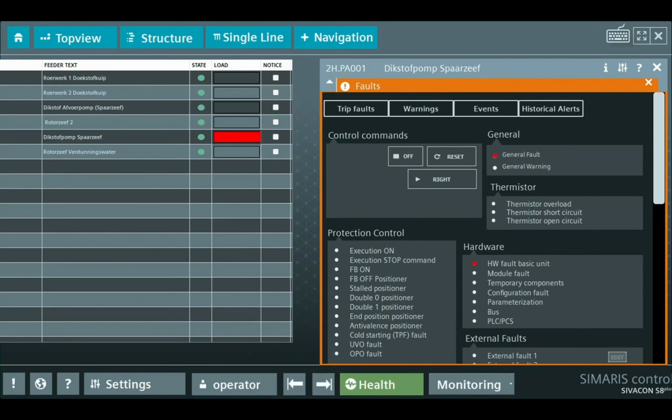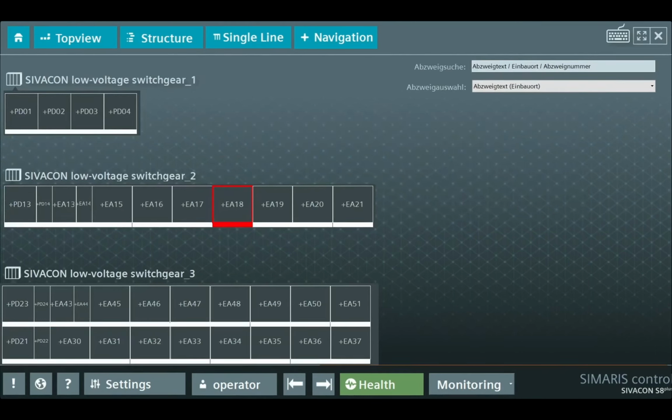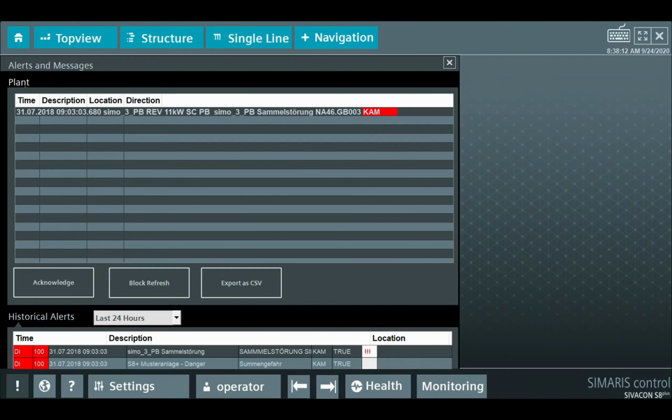Now we measure the current. Alarm events are monitored throughout the entire system using this hierarchy, from the current transformer, and we connect the device via the current transformer to our protection relay. I draw here parts of a protection device. You see here an input transformer, the measuring input, the connection point where the relay measures the current which comes from our current transformers. This allows the user to quickly identify where a fault has occurred and initiate countermeasures using the detailed fault description. All existing alarms and warnings are also collected and archived in a central alarm list.